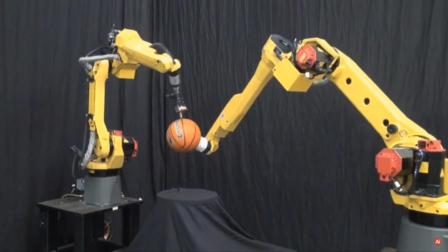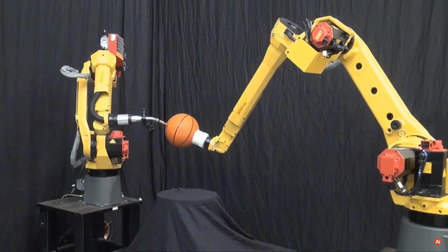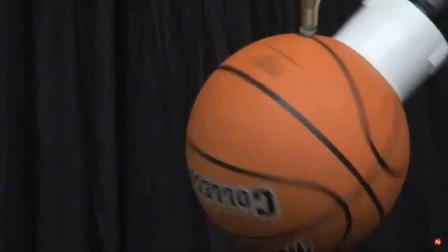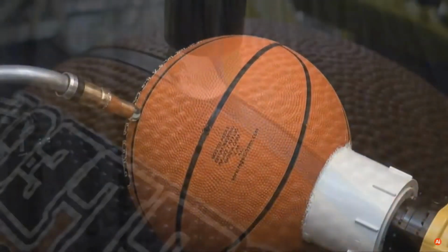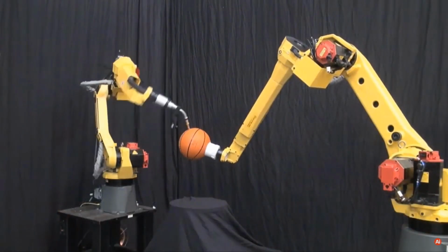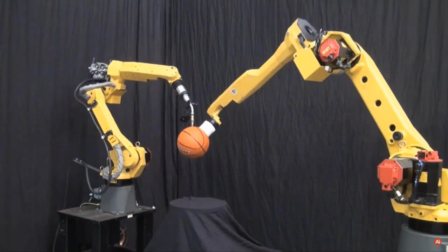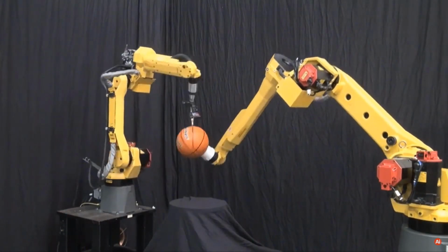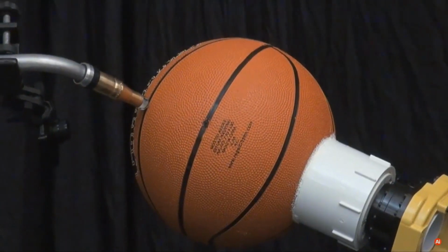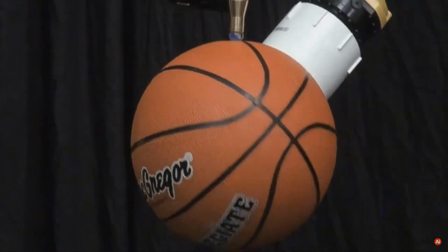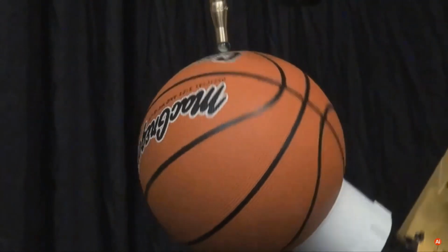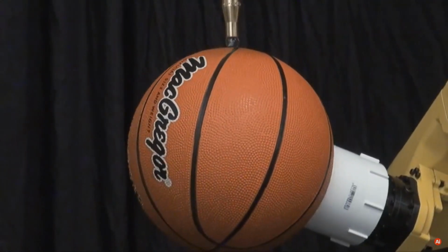As you can see in this video, we have two robots. In order to have coordinating motion, you need to have a leader and a follower. In this case, the robot on the right that's holding the ball is the leader, and the other robot with the TCP following a trajectory on the ball is the follower. Both of them work together in such a way that the follower robot follows the pattern on the ball with the TCP perpendicular to the surface of the ball. Also, it doesn't matter if the leader robot moves, the follower robot maintains the relationship with the leader.